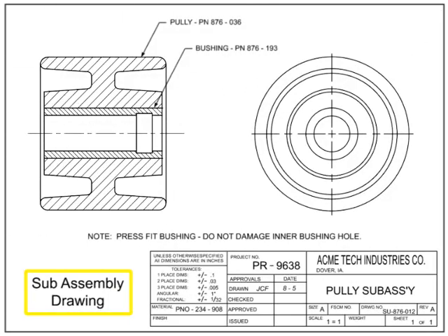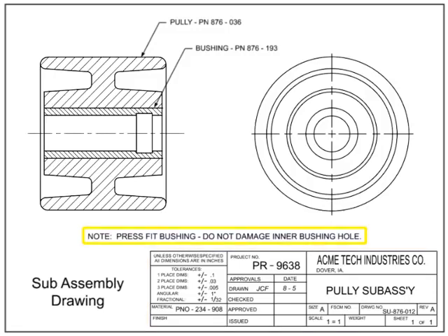Sub-assembly drawings are made of two or more separable items that join to form a sub-assembly that is then used on a higher-level assembly. Sub-assembly drawings are useful for smaller assemblies that may go on multiple end products, such as a hydraulic valve that goes on many different tractors. One of the differences between an assembly and subassembly is that a subassembly typically has the use on or next higher assembly called out either in the title block or in the notes section.